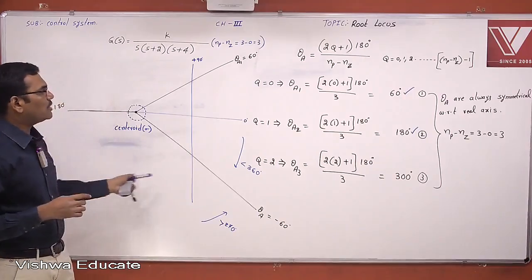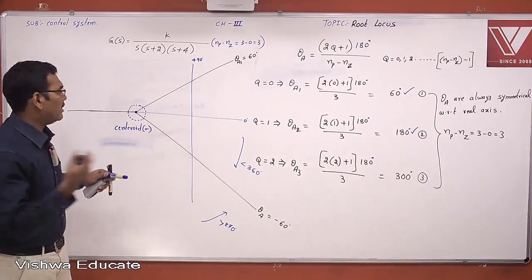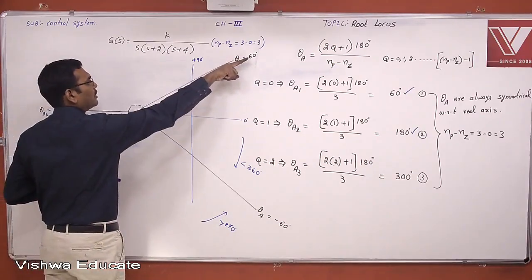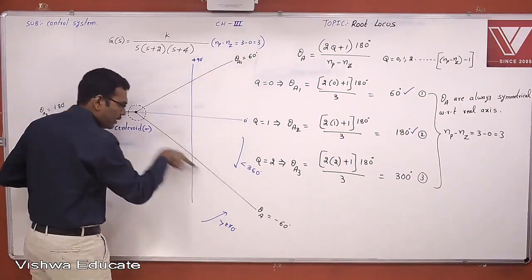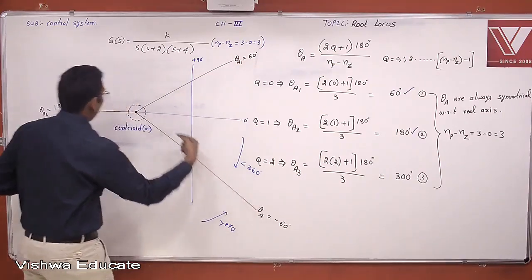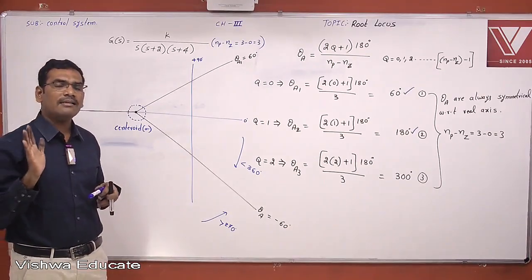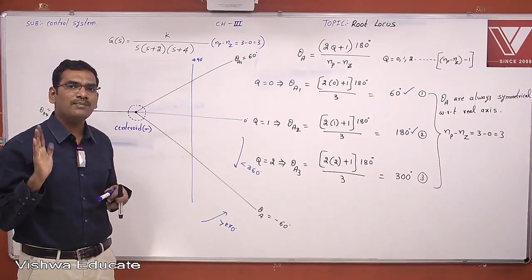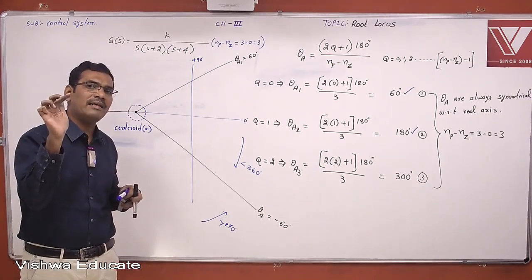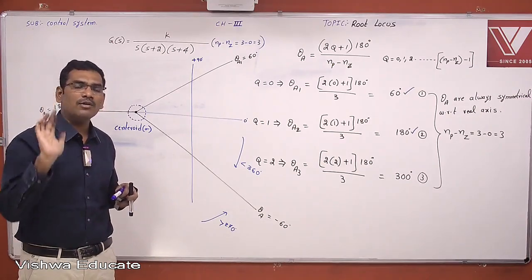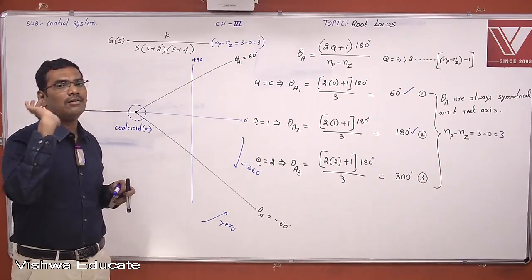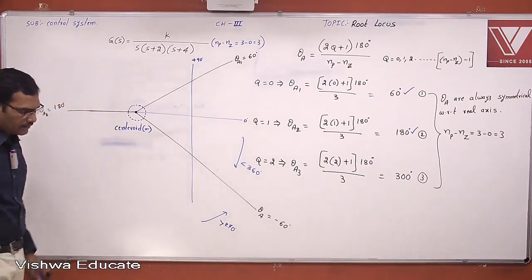First, you just verify this. Now you can understand. If you go in this particular direction, you will definitely meet a zero. Angles of asymptotes are the directions in which the root locus branches are moving. You will meet a zero, and the root locus diagram terminates at an open loop zero. Note this down.